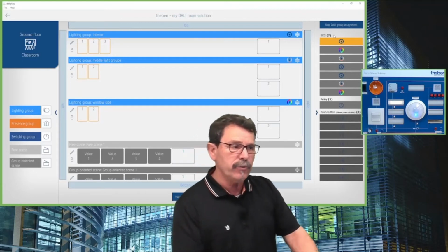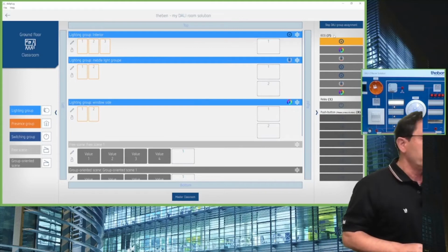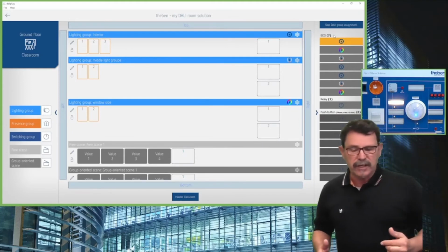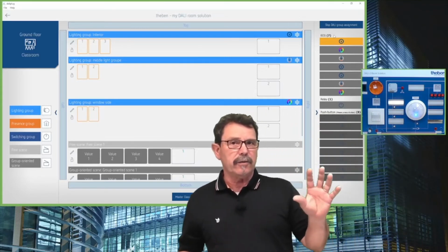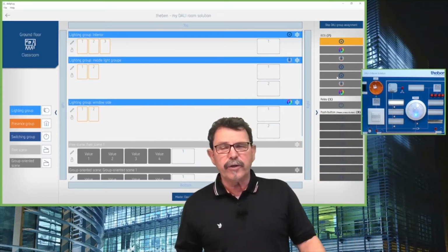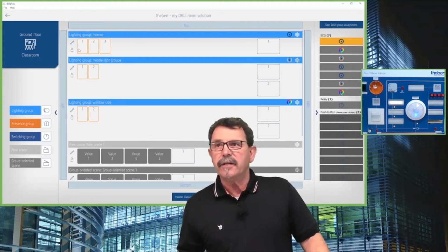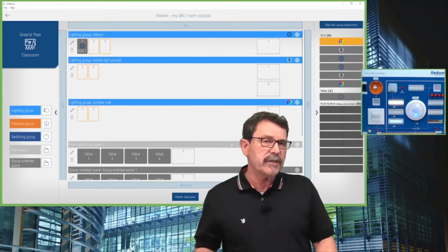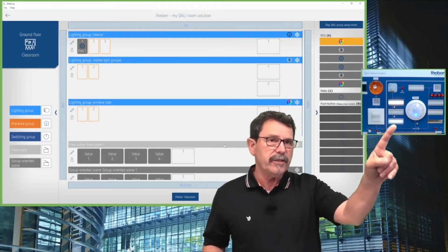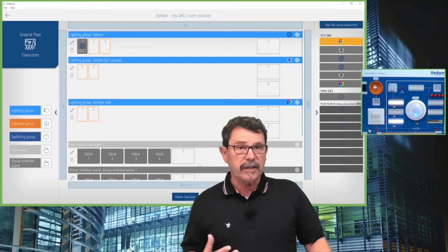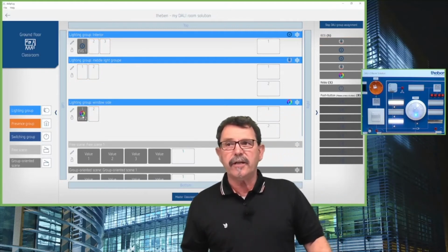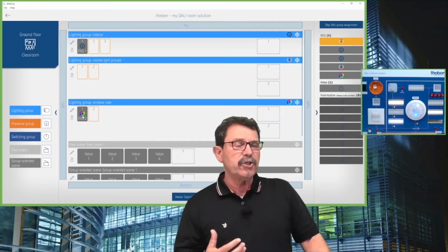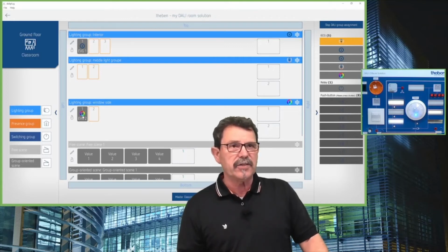And then probably you will discover that we do have here a flashing light. This flashing light tells me, okay, it's me now. So where I want to allocate this. Okay, this is this one here. Then the next one is flashing. So you discover here on this side, this one is flashing. So it's a colored light. So I just have to click in this frame. Okay, done. So that means exactly now this light, the switchgear, gets a short address from the DALI system.